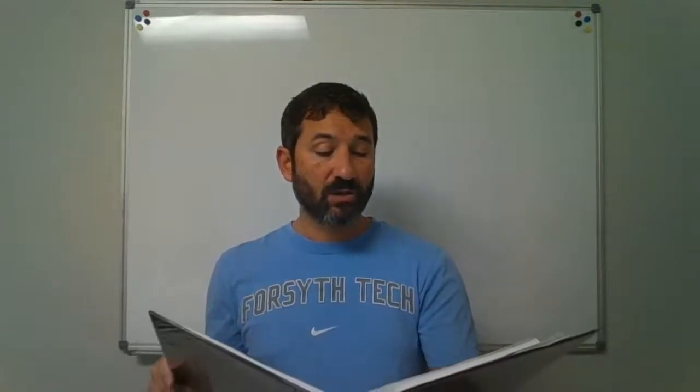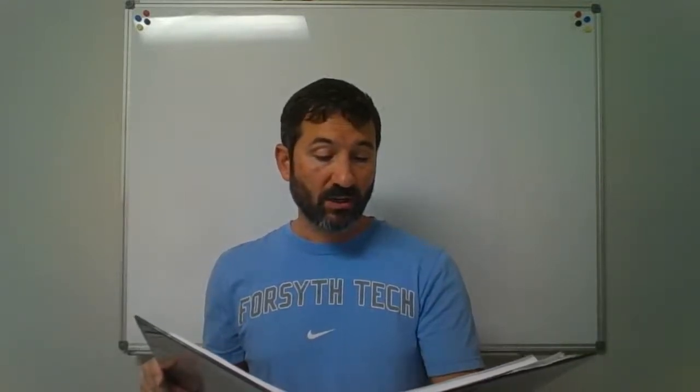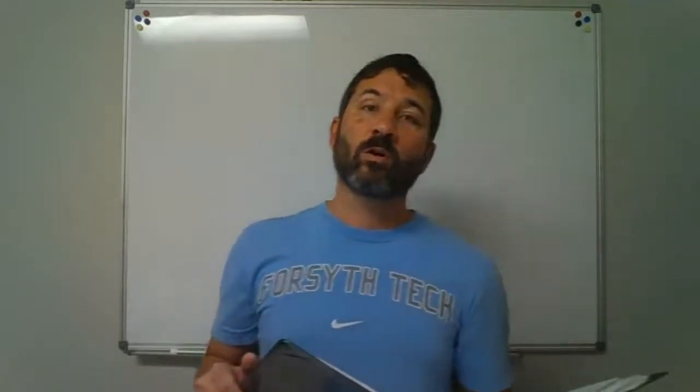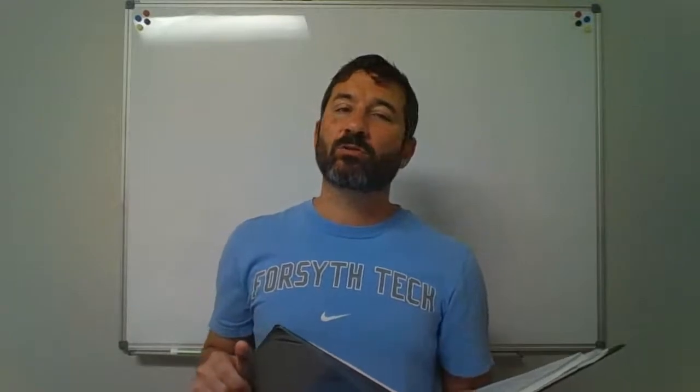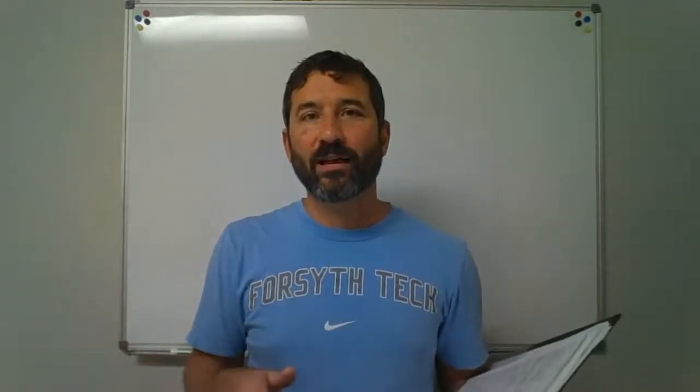Okay, conductors and connections. Prohibited use. Conductor pipes shall not be used as soil, waste, or vent pipes, and soil, waste, or vent pipes shall not be used as conductors. The floor drains shall not be connected to a storm drainage. So we aren't allowed to, and I know you'll probably see some older basements at times where they had a floor drain in the house. And then if they had the side of the steps that kind of went down and they had a drain just outside the steps to where if water rained, it could pool down in there at the bottom of the steps going down to the basement. And a lot of times those were connected together.